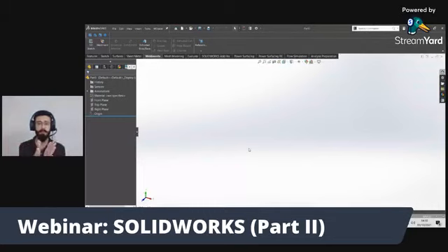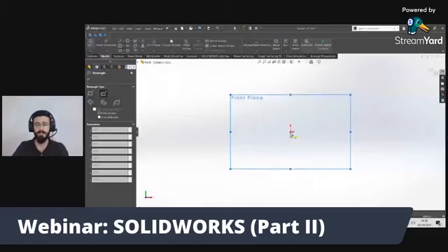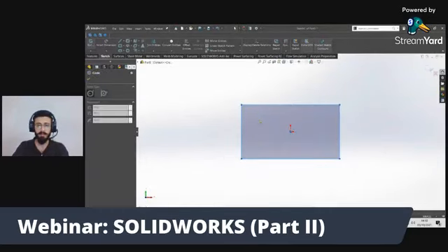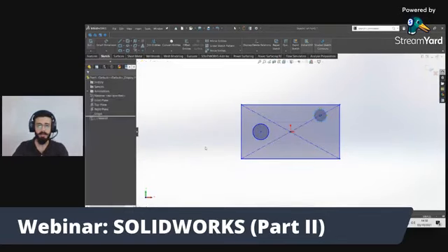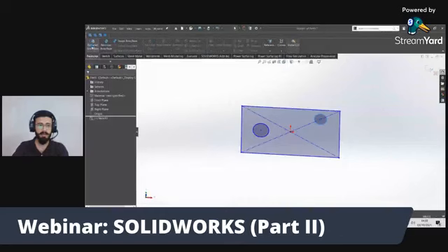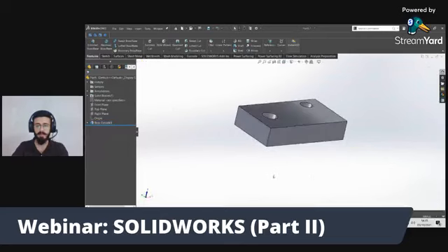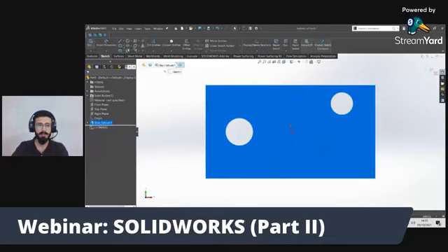First you have to model your design. Let's suppose we are using the front plane, making a kind of sheet. This is our design. There is one hole here and one hole here. That's it. And then extrude it, just 20, 40. That's it. This is our design. So just add a bit more features here, make it a bit complex.